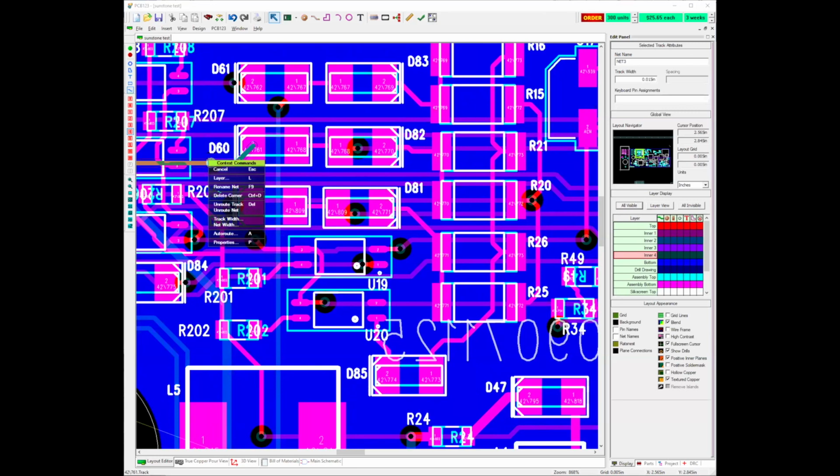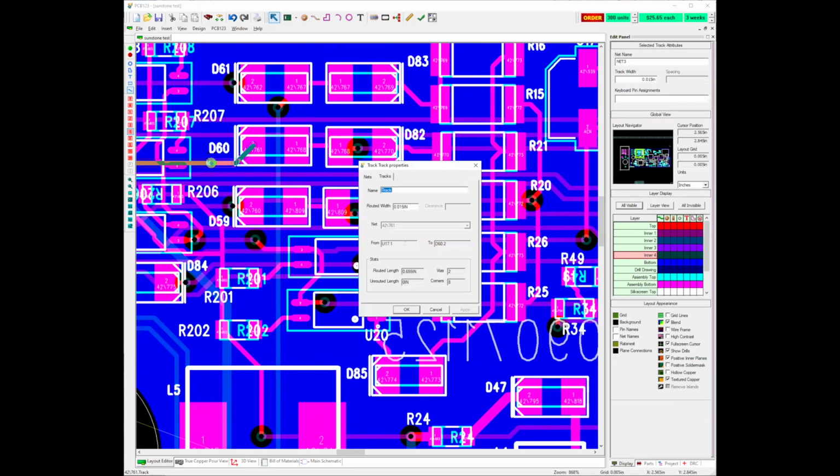What I don't have is anything that tells me, let's see, properties on that wire. You can basically just select the wire, right mouse properties, and it will tell you what the via that you're using on that wire is. So on this wire, I'm using a trace width of 15 mils is my standard width.